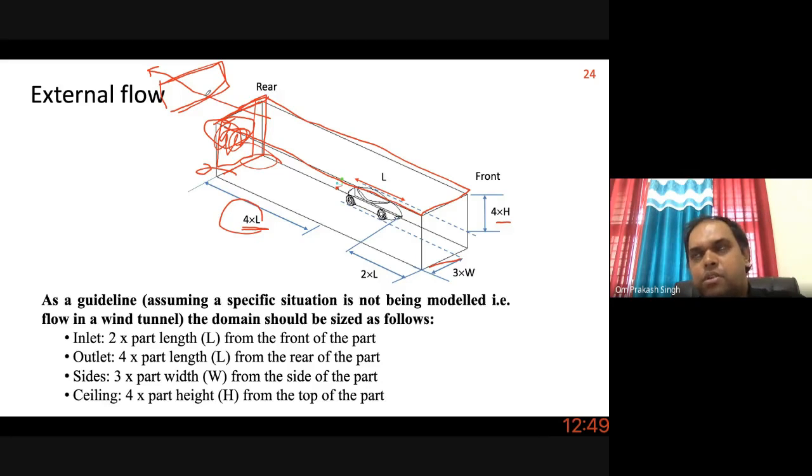That is also one of the aspects of dealing with a convergence problem. You have to check whether the boundary condition you have applied is physically correct or not. In this case, if you apply a constant pressure boundary condition just here where there is a reverse flow, then that boundary condition, though it is correct as per your problem, is not physically correct because you are imposing it on the entire wall,